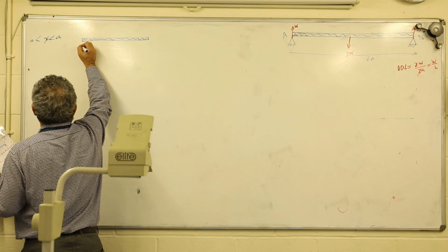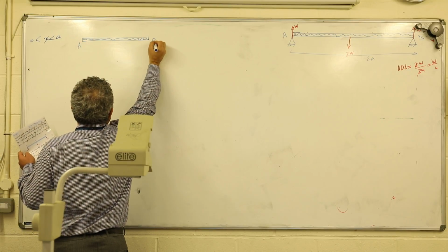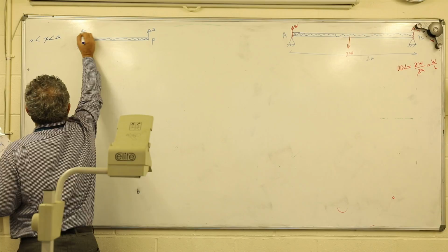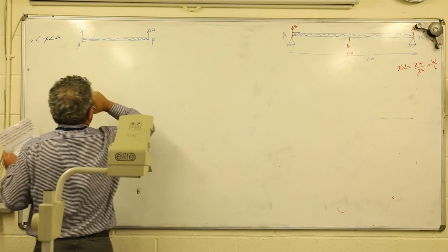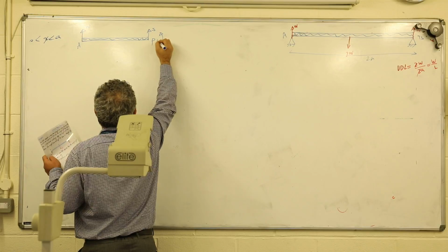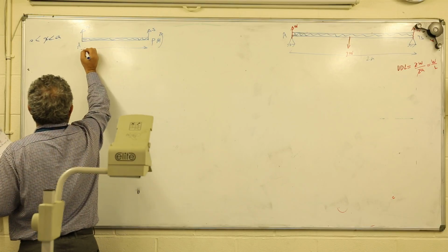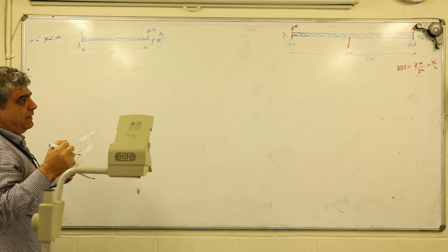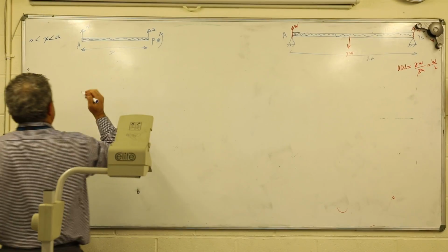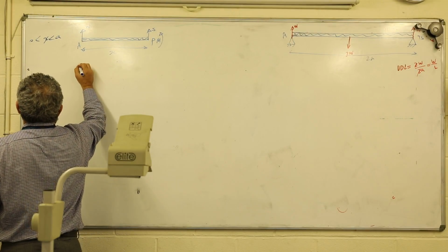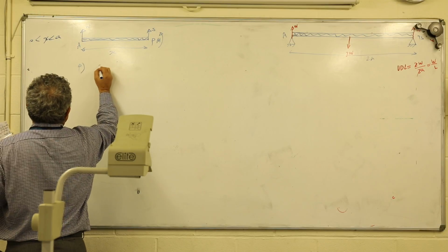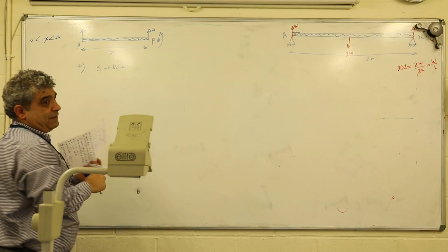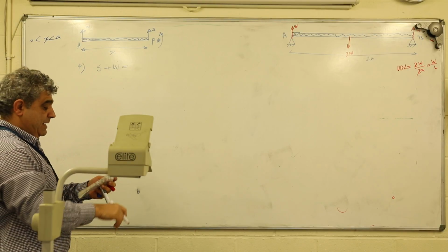And this is point P, the point of cut. There would be a shear force here, and there would be a reaction force which we already got, W. And there's a moment here as well, and the distance I cut is called X. As simple as that. Then I'm going to solve it. So the equation of the shear force for this one: S goes up, W goes up, and something goes down here, which I have missed. I haven't put it there, but you have to put it.